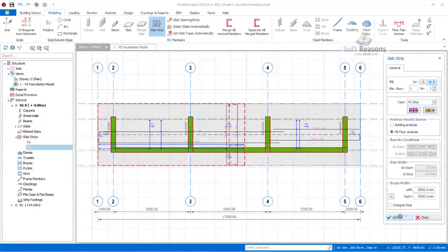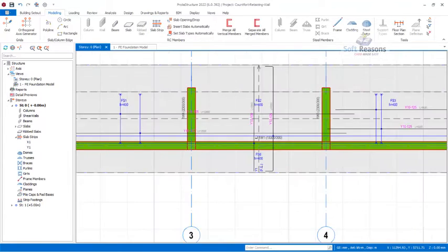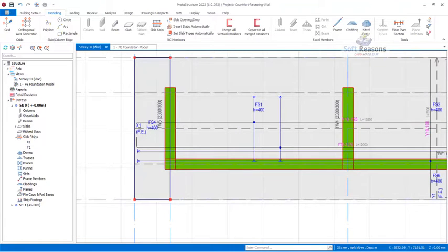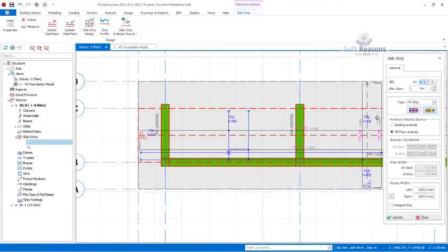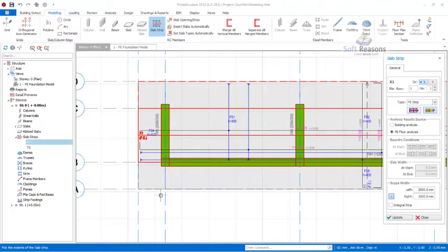right there. All right, so after which we will also extend the horizontal strips. So select, close that, and then select the horizontal strips, which is this one. Get it selected, right click, and then click on this property. So in the property, pick these provisions, and then pick that point, and then update right there. Pick this, and then pick this end and update right there.